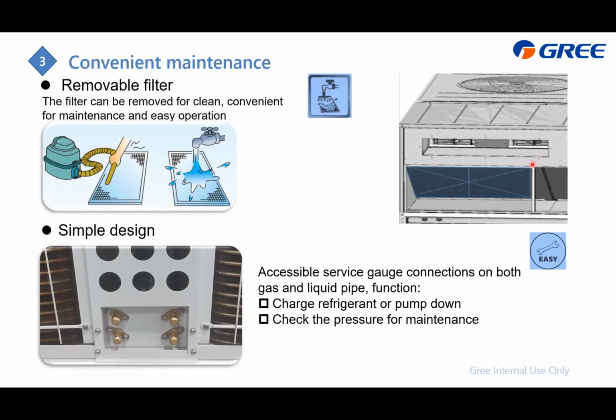As for the inside filter, it is allowable to remove for wash, or you can use a vacuum to clean it, just like this. And on the rooftop unit, we offer the service port for you to check the high and low pressure and also to charge the refrigerant and to do the pump down operation.